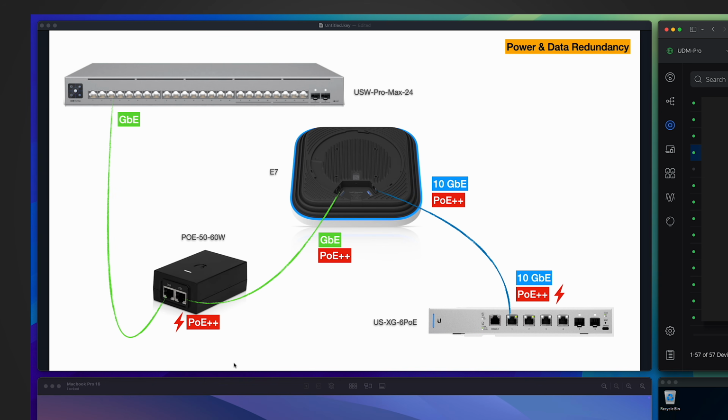So the total power consumption from this adapter and this PoE port, the sum is what the E7 is using. So it's more than 20 watt, similar to what we had before enabling the high availability, right? So now the power consumption puzzle has been resolved. As long as you have both PoE++ connections, the system will automatically distribute the power consumption to the 2 sources.